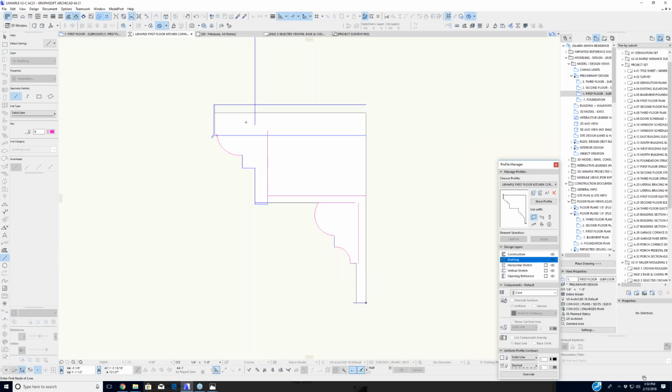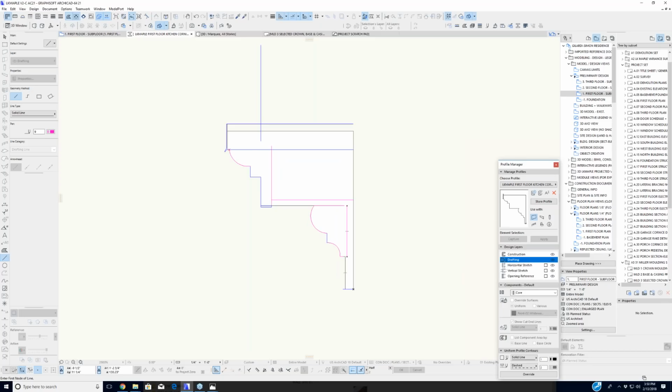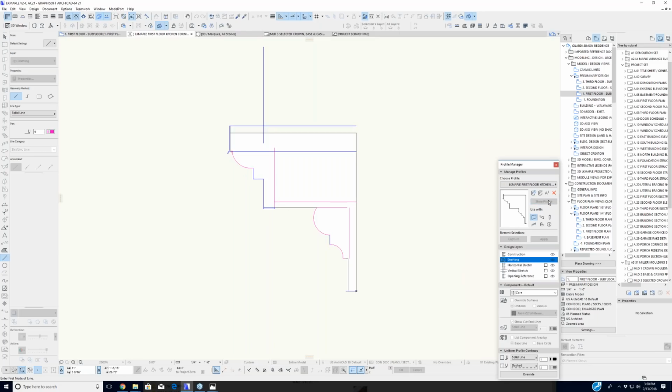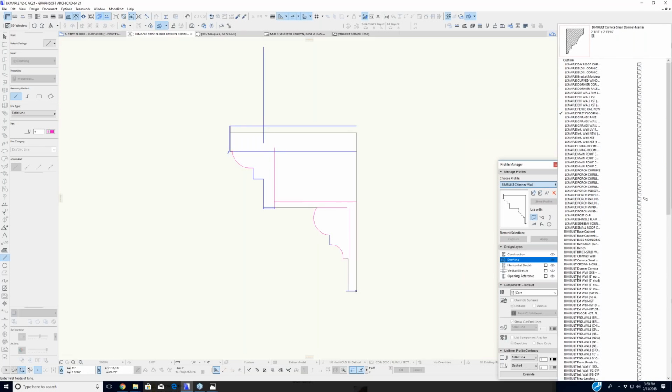And then I could break that out and get this to be exact, all of these little parts. The reason I don't do that here is it wasn't necessary, and I'm not 100% sure what was behind all those moldings to start, assuming this one's an inch thick, that type of thing. So basically, if the element is going to be constructed and they need to make it out of pieces, then you can do that. On the other hand, if you're modeling an existing thing, then you really only need the outside volume to show up, because you're not going to be cutting through that existing element. So it functionally appears in the model.